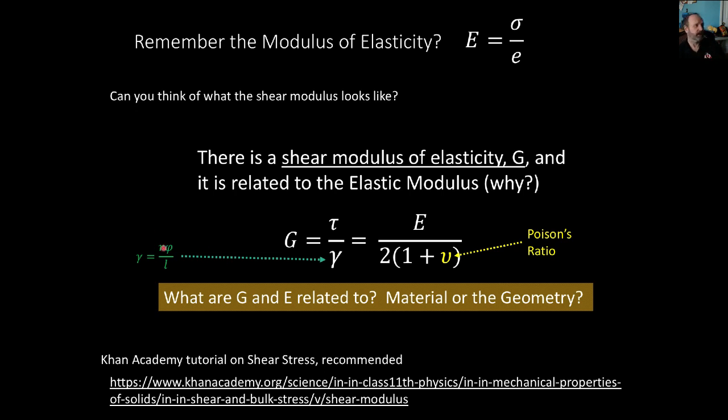Okay, but it's the angle of twist times r divided by the longitudinal distance over which you're shearing. Okay, so that's in the denominator, and then this is the shear stress in the numerator. And remember, that was torque over 2 pi r squared t. Okay?